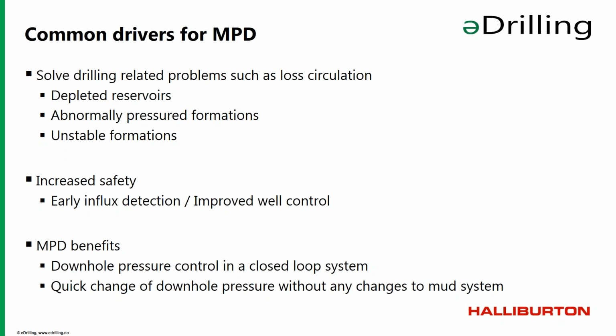It's also a technique which is used for wells where you have a narrow margin between the pore pressure and the fracture pressure. By using MPD, you have increased safety, you get early influx and loss detection and improved well control. By using the MPD technique, you have downhole pressure control and a closed loop system, and you can quickly change your downhole pressure either up or down without any changes to the mud system.